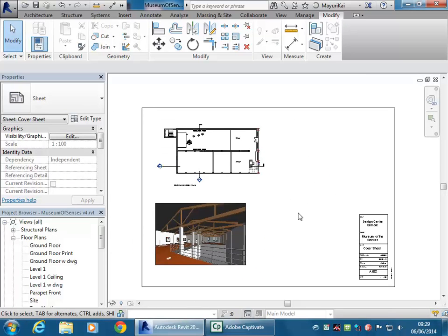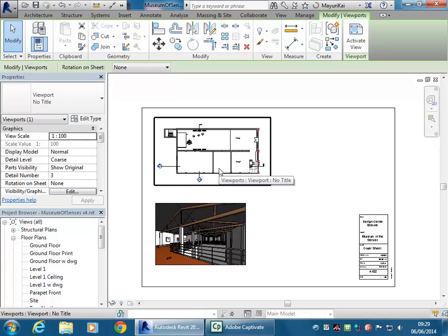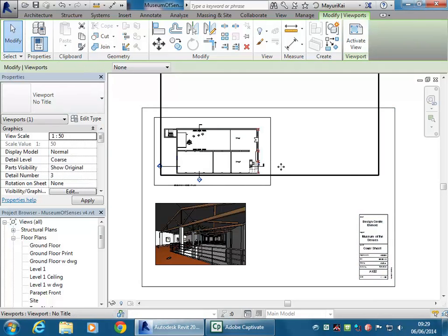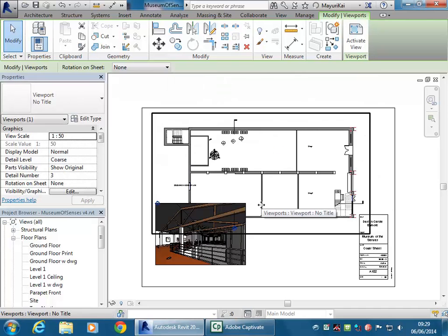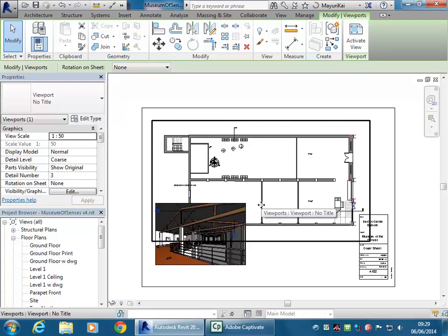So we won't fit to floor plans on A1. Oh, you should. If they're 1 to 100, you will. But yeah, not 1 to 50. I'd say we have to make it 1 to 50. Ah, right. Well, you'll see here now. If I change this to 1 to 50, you'll see exactly what you'll fit. Yeah, it's big. 1 to 50 is a difficult scale to work with. So you will fit one level, and maybe a couple of other little perspectives or something. But that's about it.